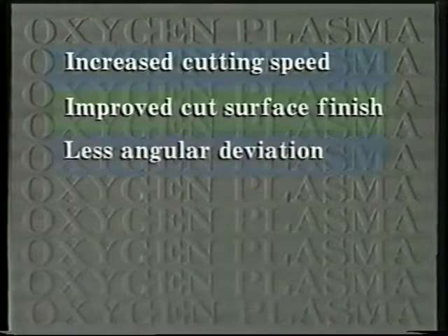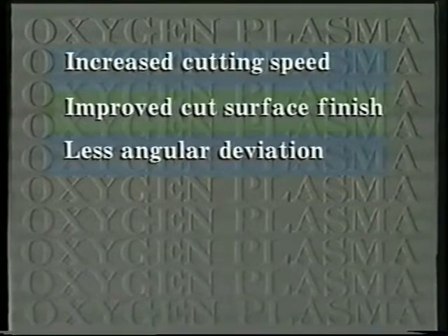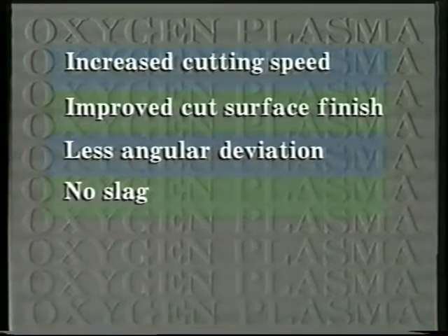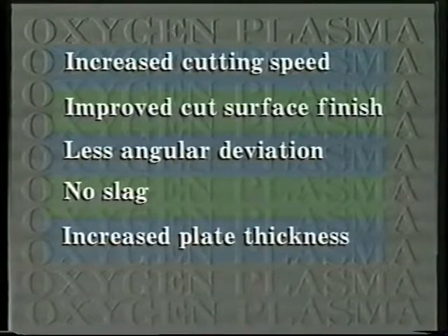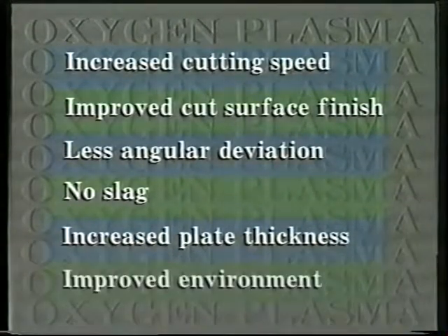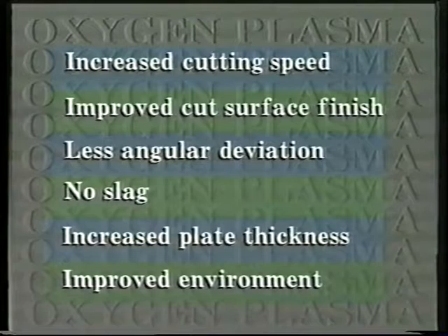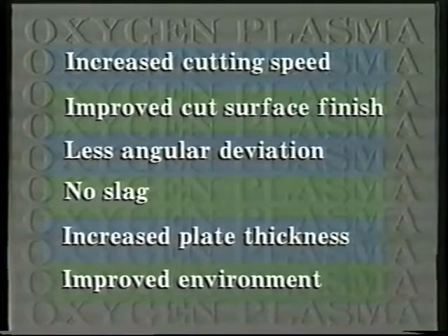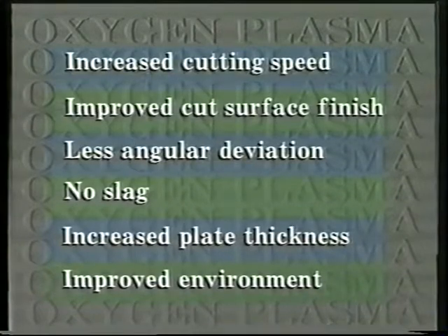Let's review the many advantages of oxygen plasma as compared with air plasma. Increased cutting speed, improved cut surface finish, less angular deviation, no slag, increased plate thickness, and an improved environment. This method not only boosts productivity, it also ensures end products of the very highest quality.